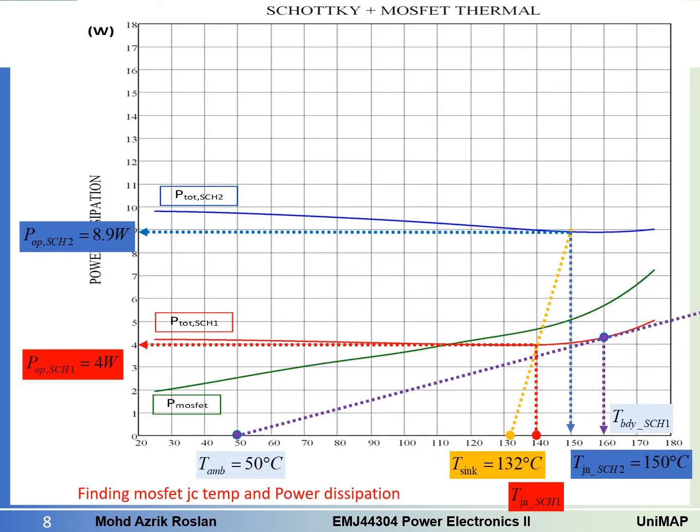So that one we have to draw here. This is the temperature of the heat sink, and we know that at this point this is 132 degrees C. So if we want to have the increment of 3 degrees C, it is 132 plus 3, which is 135, which is in the middle here, in the middle of this box from 130 to 140.